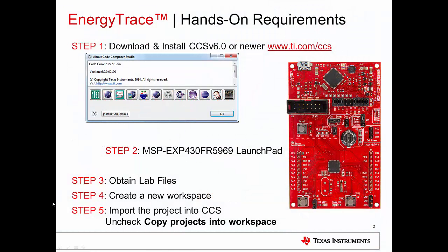So before we get started, I want everyone to make sure that they have the proper environment set up. In our case, we're going to be using Code Composer Studio 6.0 here. And you can actually download it from www.ti.com/ccs. That's the first thing.